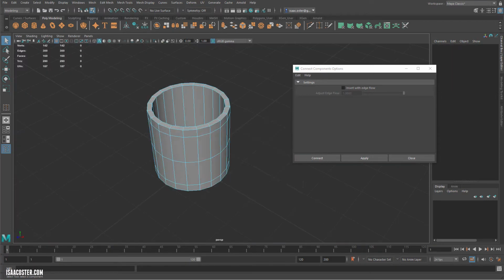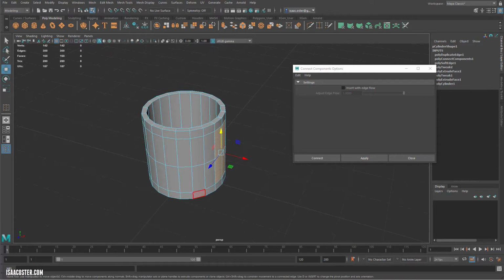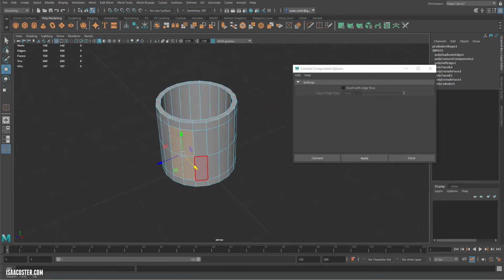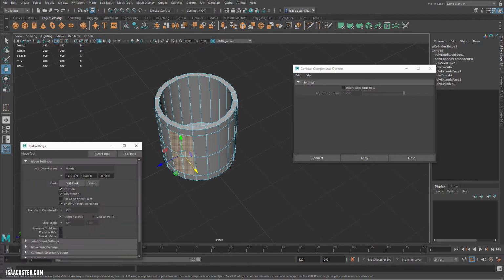All right. So that doesn't make too much difference, except if I'm grabbing some of these faces and I want to do something with them, if I tap the W key to go to move mode, and I'm either on the side facing axes or the front facing, this is already going to be kind of lined up so that I can use the tools here, as opposed to something like this, right? Where if I were to come over and grab the tools, it's going to pull off at some kind of odd angle there. So that's not to say that you can't change this.